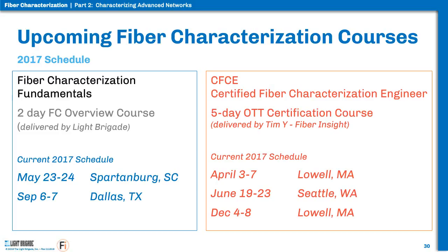Just because someone agrees to lease you or sell you a G.652 fiber, and that's what they tell you that you have, doesn't mean that's what it is. I have real-life examples in the field with clients who thought they had G.652, and they went ahead and bought components. They bought dispersion compensators based on that, and after we tested it later, we found out that it was perhaps a mix of G.652 and G.655. Again, it's a good practice to test this to validate what you really have, so you can plan better, so you can engineer more accurately, and you're not having to redo things after you find out the hard way.